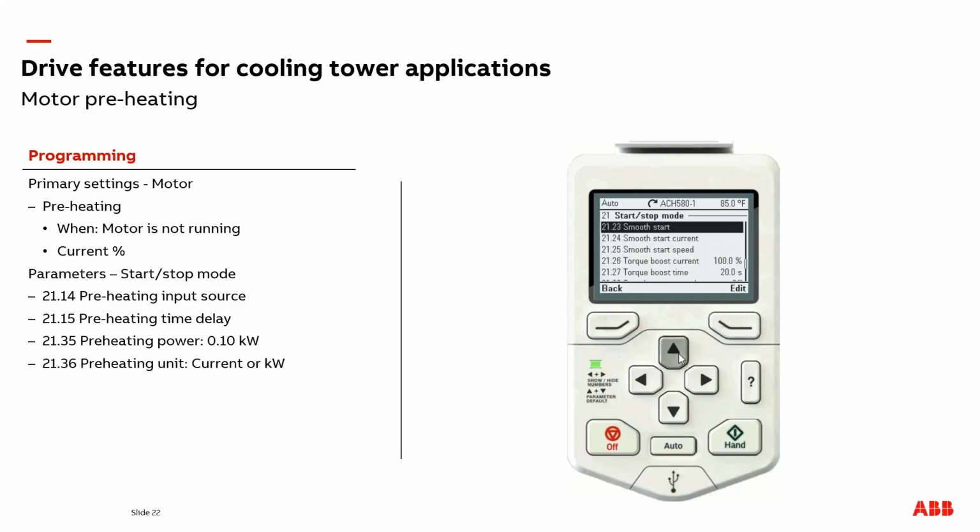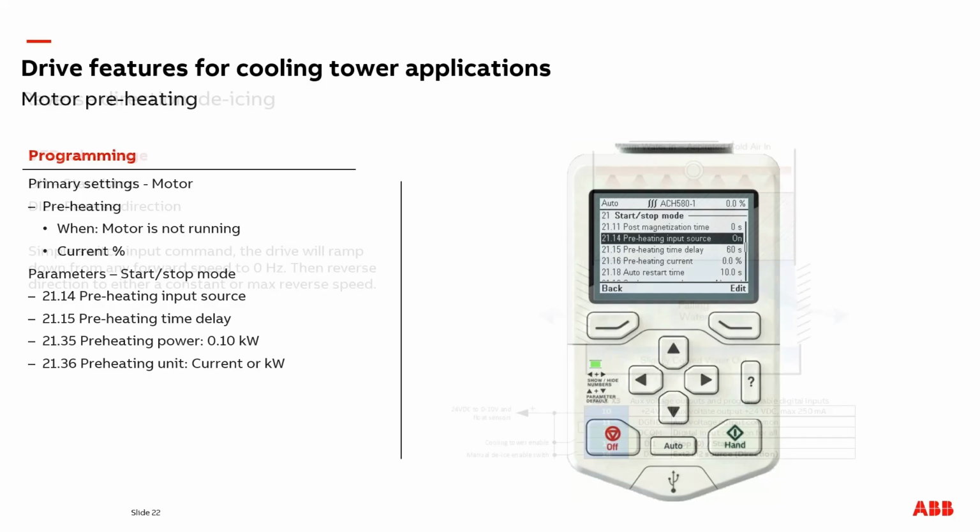Select save, scroll up to enable motor heating, which you cannot adjust the power amounts while it's enabled, and activate it. When the motor heating is activated, a warning message will be displayed on the keypad indicating that it is active, as well as an icon will show up by the drive name. You can hide this screen to continue making adjustments.